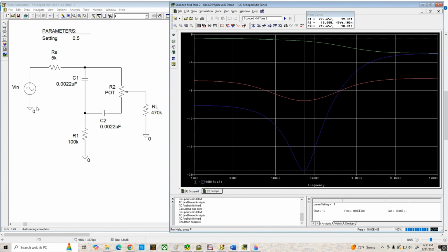Now, if we happen to be trying to drive this tone control with an op-amp, say, they typically have extremely low output resistance, close to 0 ohms, and in that case this tone control circuit wouldn't work unless we added an external RS here in series with the output of the op-amp. But that's a topic for another day.